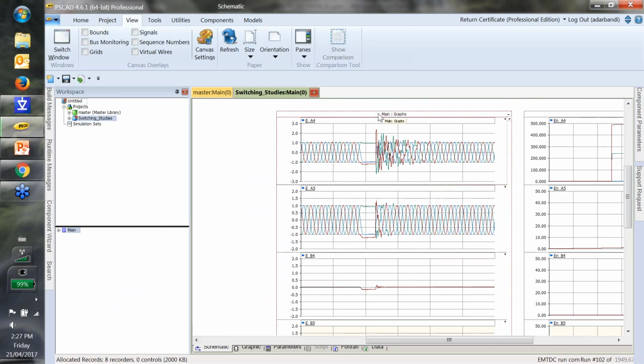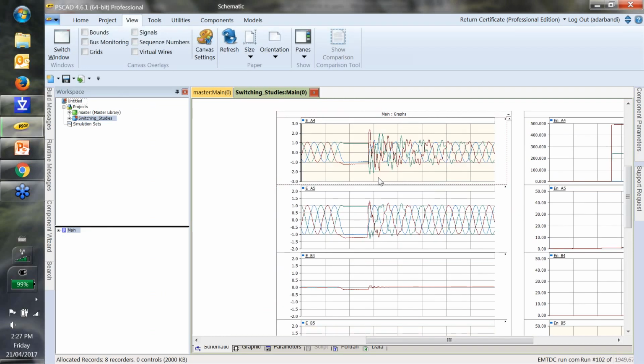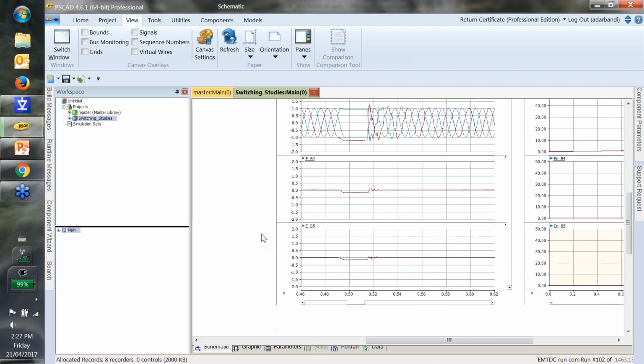So this is the voltage for the worst case scenario. We see we have a trapped charge, and it appears the maximum overvoltage at the opening end is close to 2.2 per unit. The line out of service does not show much voltage induced on it, as expected.